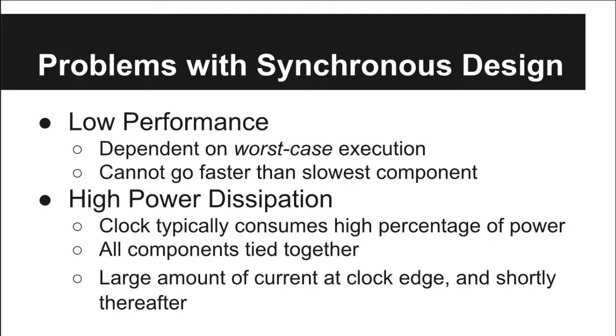Performance is greatly dependent on the length of the critical path, meaning performance can't improve beyond a certain point, regardless if the data path actually uses the full critical path or not. So that means there is a lot of time the circuit sits idle, waiting for the next clock pulse, and this results in wasted time and performance potential.